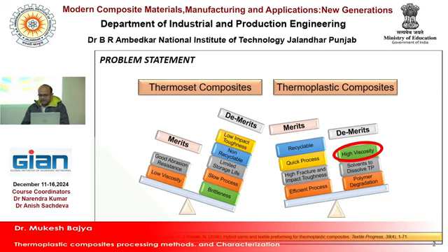The demerits are the higher viscosity, solvent being required to dissolve the thermoplastic, and polymer degradation, because thermoplastic composites are temperature sensitive materials, so we need to take care of the processing temperature and everything.